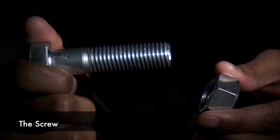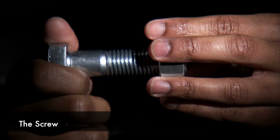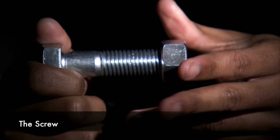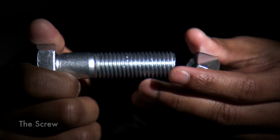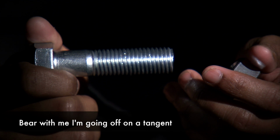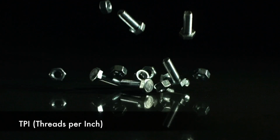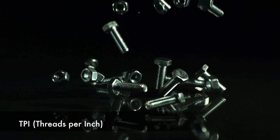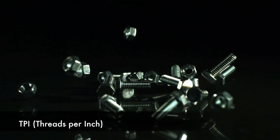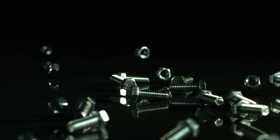The screw is usually a circular cylinder member with a continuous helical rib and is used either as a fastener or as a force and motion modifier. TPI stands for threads per inch. This is simply a count of the number of threads per inch measured along the length of the fastener. TPI is used only with American fasteners. Metric fasteners use thread pitch.